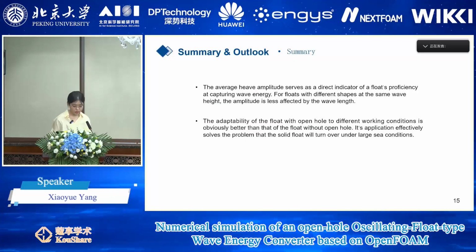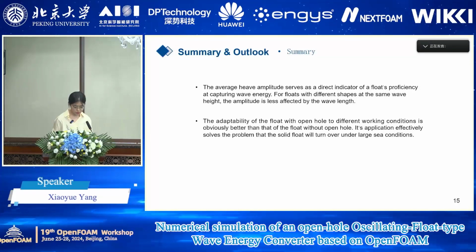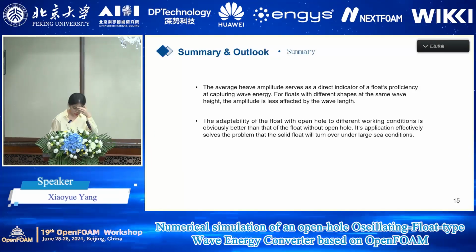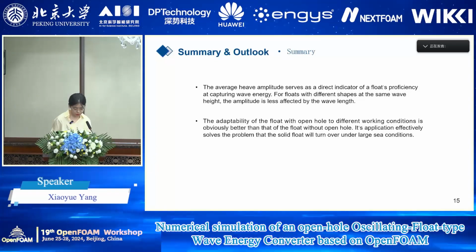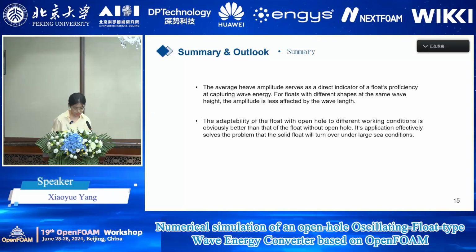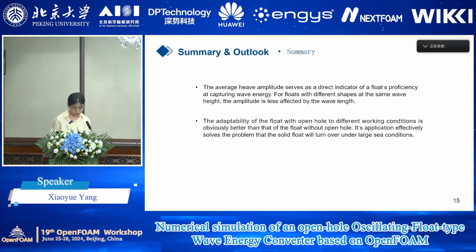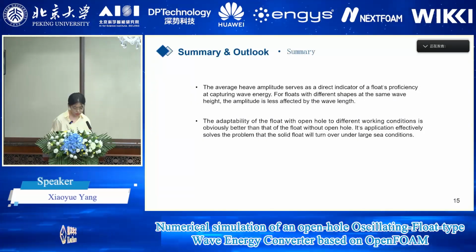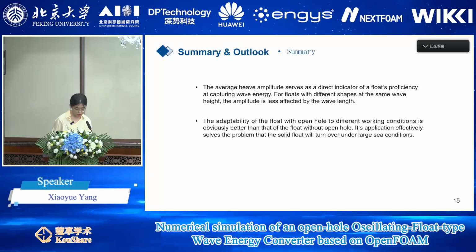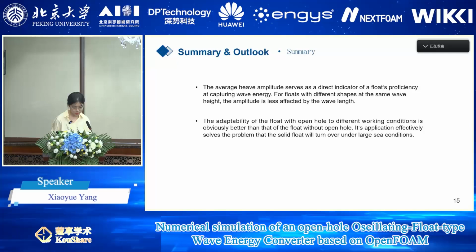And we can come to the following conclusions. The average heave amplitude directly reflects the capture ability of wave energy. For floats with different shapes at the same wave height, the amplitude is less affected by the wavelength.